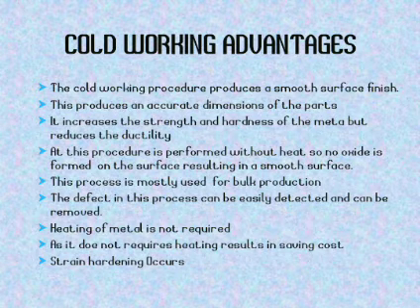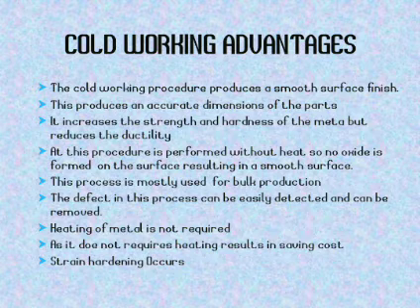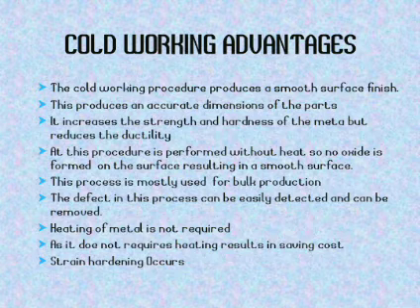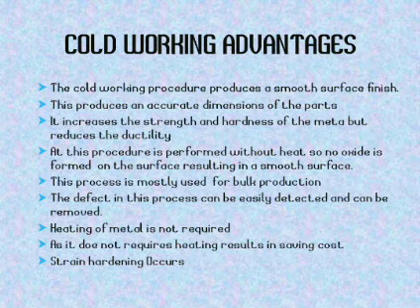As this procedure is performed without heat, no oxide is formed on the surface, resulting in a smooth surface. And also, this process is mostly used for bulk production, and the defects in this process can be easily detected and removed. Heating of metal is not required, so it results in saving cost, and strain hardening occurs.